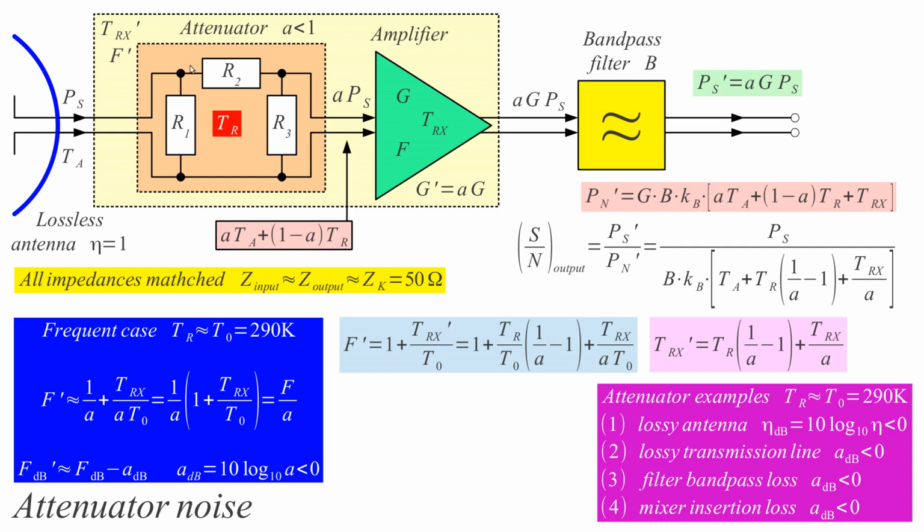And this coaxial cable is also a lossy transmission cable. We may have bandpass filters. All real-world bandpass filters have some transmission loss. We want to have a low bandpass loss in the bandpass filter, but this is unfortunately not equal to 0. We still have some loss, and we may have passive components in our radio.